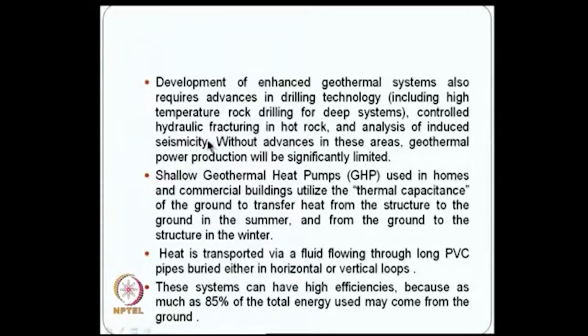Development of enhanced geothermal systems also requires advances in drilling technology. The conventional technologies are not adequate. So, you may have to go for high temperature rock drilling for deep systems, controlled hydraulic fracturing in hot rock, and analysis of induced seismicity. You need to do hydraulic fracturing, breaking of the rocks in a controlled manner, but the more you introduce fractures, the more it leads to some sort of seismicity, and plate tectonics should not be affected. Like we had the classical case of reservoir induced landslides, that should not be the case here. So, one needs to understand that there should be a controlled way of doing this.